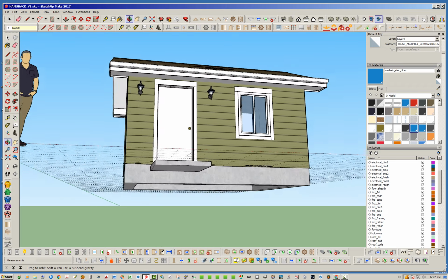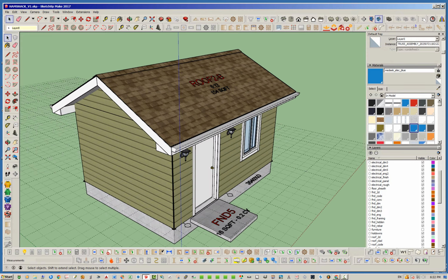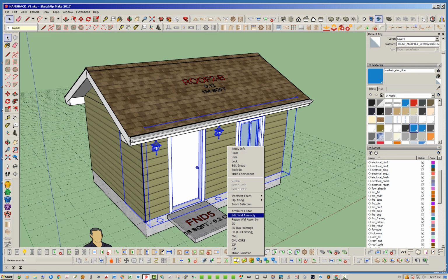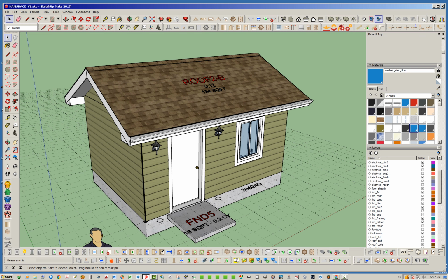The only thing is I'm not a huge fan of an 8-foot ceiling. So what we're going to do is change that up. I'm trying to remember what the default stud size is for a 9-foot ceiling. Let me see, 9 foot. I'm just pulling this up on my browser over here. Stud height, sorry. I think it's 104 5/8 of an inch is the standard. And I think these ones, if I remember right, are 97 1/8. So the 97 1/8, by the way, is the standard stud height for an 8-foot wall.